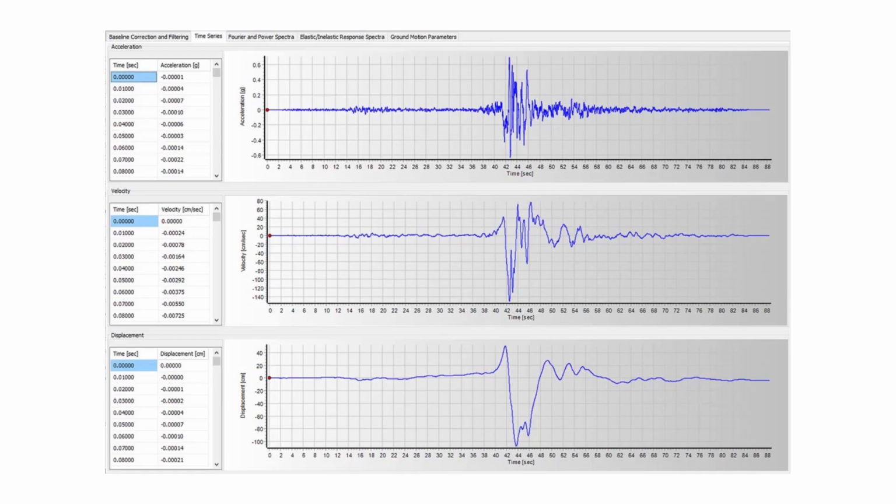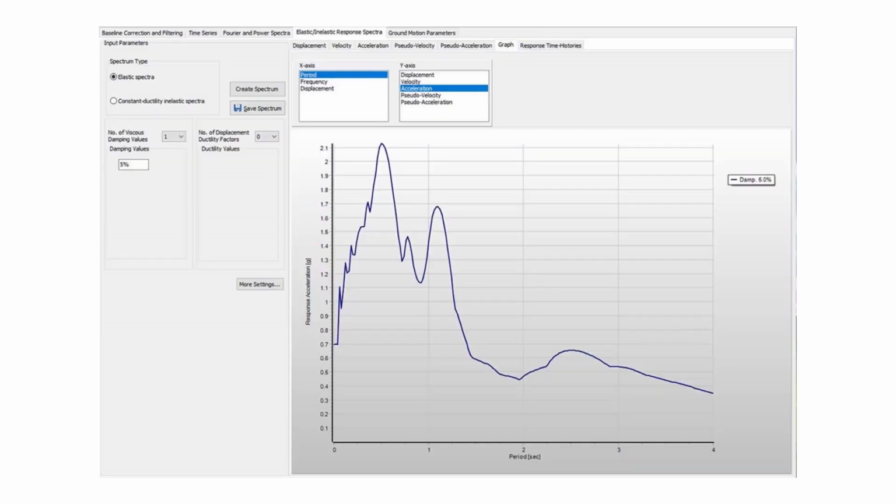You can see here these are the different seismic responses. The first one is the acceleration response, second is the velocity, and third is the displacement response. And all these are the ground motion data. These ground motion data can be converted into the corresponding spectral acceleration. So this plotting is performed by using different numerical techniques and computational procedures by which you can convert the seismic historical data into the spectral acceleration data.